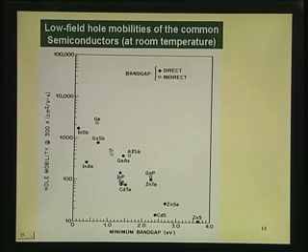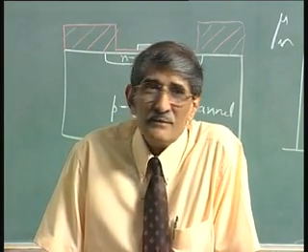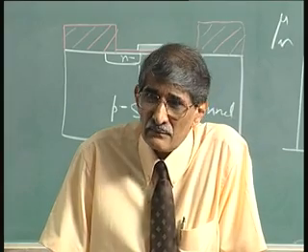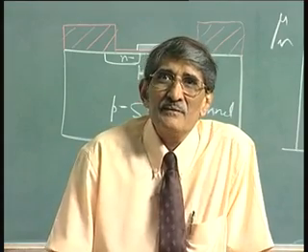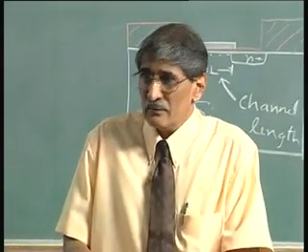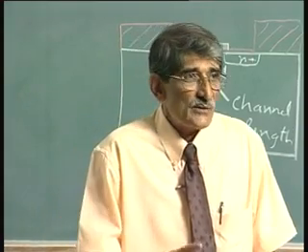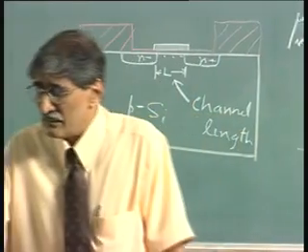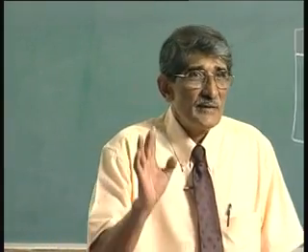So, you see, you jumped up with joy when you saw the gallium arsenide having electron mobility much higher than that of silicon, but you look up the hole mobility, it is way down. So, do you throw this material out? You do not. You make devices which depend only on electron. Do not make devices which depend upon the hole transport. So, avoid making devices which depend upon the transport of charges involving holes. Make devices which involve transport of electrons. So, that means you are in business. That is why I just put this diagram to tell you that do not think of making CMOS with gallium arsenide, because you can have N channel devices, no P channel devices.